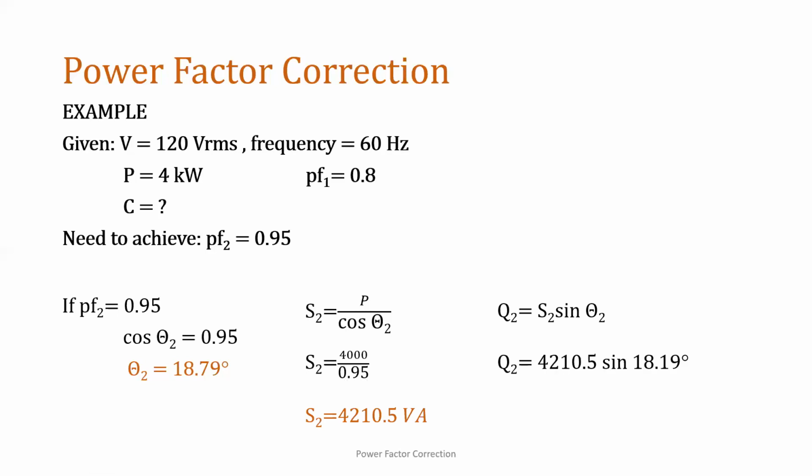Reactive power is equal to apparent power times sine theta. So 4,210.5 times sine 18.19 degrees. So we have 1,314.4 vars. So that is the new reactive power.